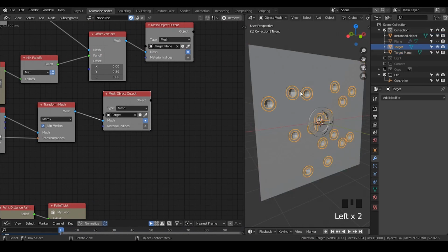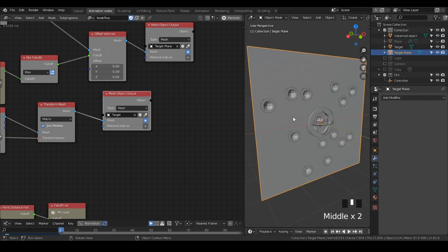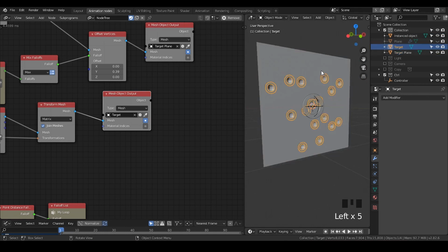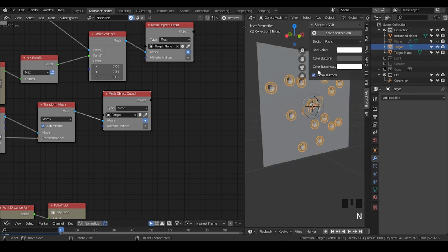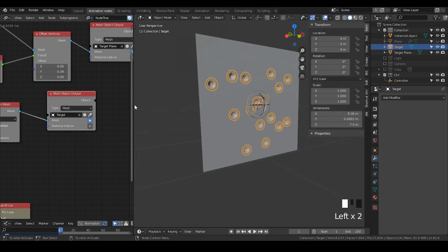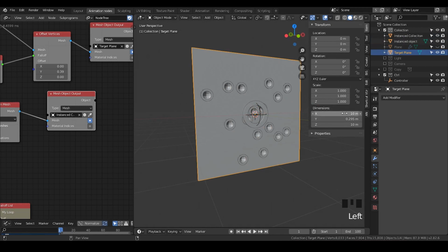The next thing is I'm going to fold everything into a sphere. But here's the one thing that you need to be aware of. If I'm folding these two objects individually, it will actually generate an error. The reason is that if I go to the N panel and look at items, now I have an instance collection, and you can see its dimension is like 8 meters, 7.5 meters, and so on. But for our plane, it's like 10.